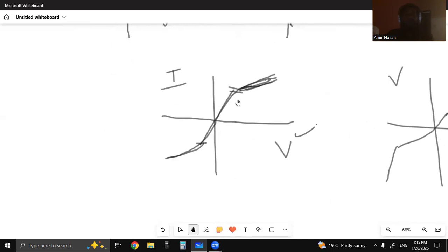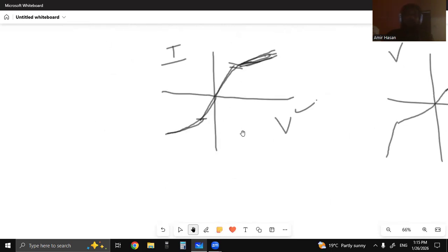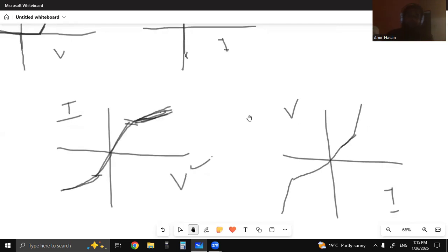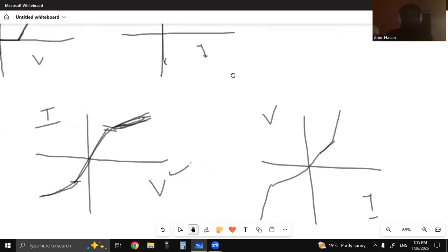At low current, voltage increases directly with current, but afterwards, when the current increases, the resistance increases, the graph changes its shape and a variable curve forms, as the current reaches a higher value and the temperature and resistance increase. Now the filament is not obeying Ohm's law.